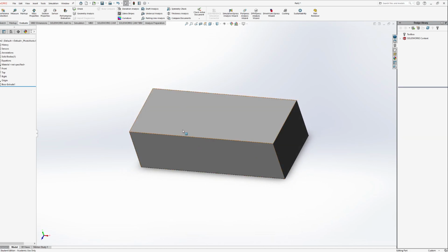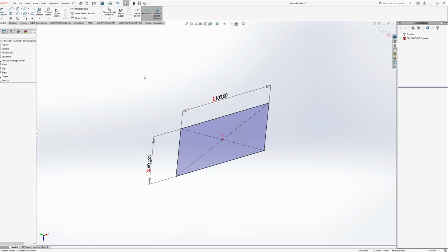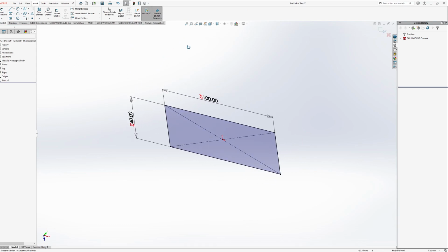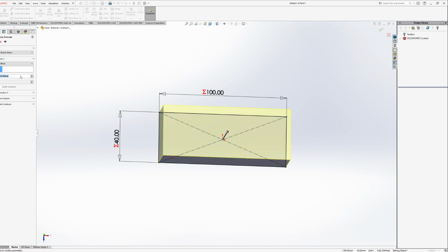If you do that, you should see, and you probably saw on your end as well, that this rectangular prism did get larger. We can verify this when I check the mass properties now. It's at 234.38. So it almost doubled in mass because of that 5 millimeter increase in all the respective directions. And I went back too far, so I will just extrude that one more time.